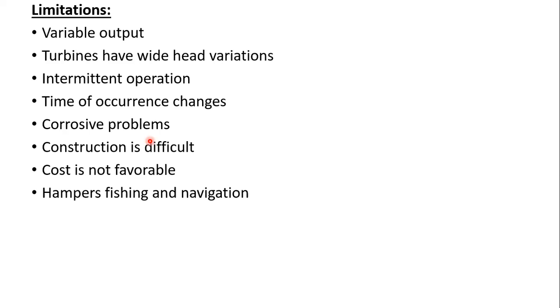For overcoming this disadvantage, we have to use stainless steel with high chromium content, and we can use a small amount of molybdenum and aluminum bronzes also. So these will be good corrosion resistance methods.